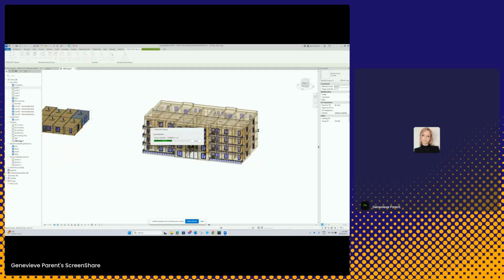The same would go for opening markers. If you're applying opening markers manually, which means if you're selecting your openings, like Control Select, and you're just applying them manually through the Apply Opening Marker, you're going to want to keep those empty as well. You really only want to have your framing and your markers in your parent group.